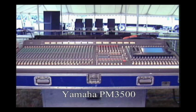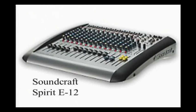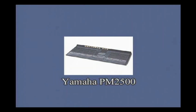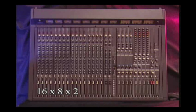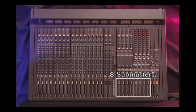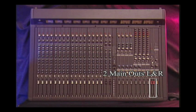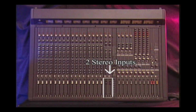Without a doubt, the main console or mixer is the brain of any sound reinforcement system. Its primary purpose is to mix, control, process, and route the signals fed into it. Here's a 16 by 8 by 2 console. The 16 refers to the number of channels, the 8 refers to the number of submasters, and the 2 refers to the number of master outputs. Essentially, in this mixer, 16 inputs are mixed down to 2 master outputs, left and right.